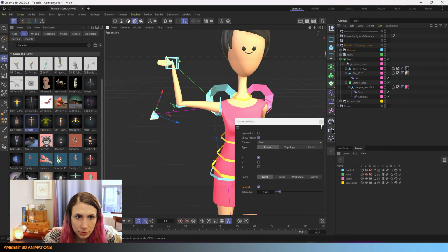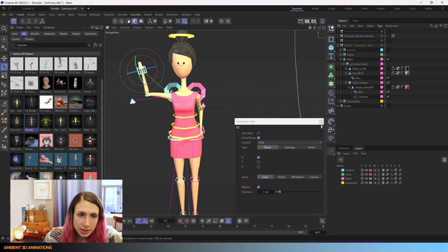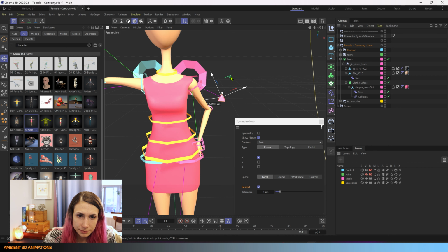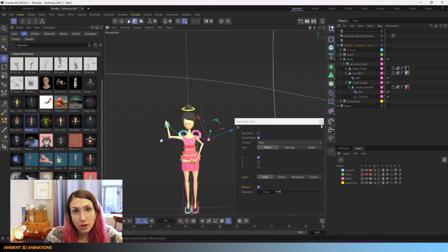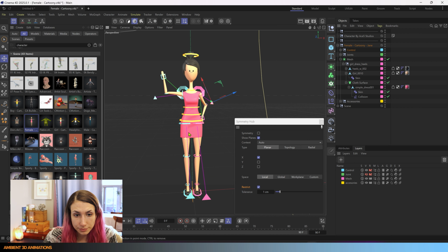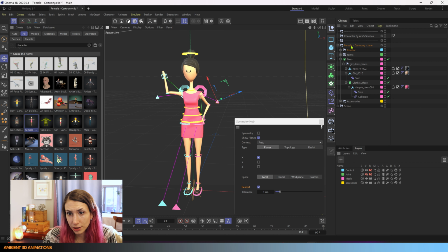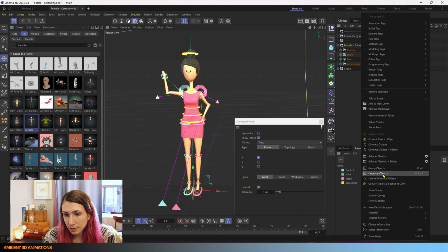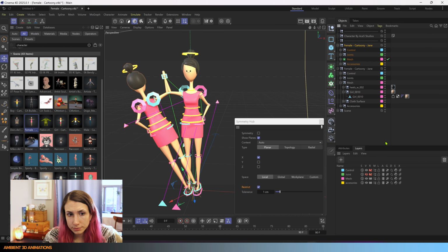That looks like it's the pose for her arm. I'll rotate this around. She has one hand on her hip and she's waving at the camera to everyone. So this character is no longer symmetrical, as you can see here. And if we go ahead and bake her down to be no longer a rig, just a mesh, I'm going to right click on this character and say current state to object.